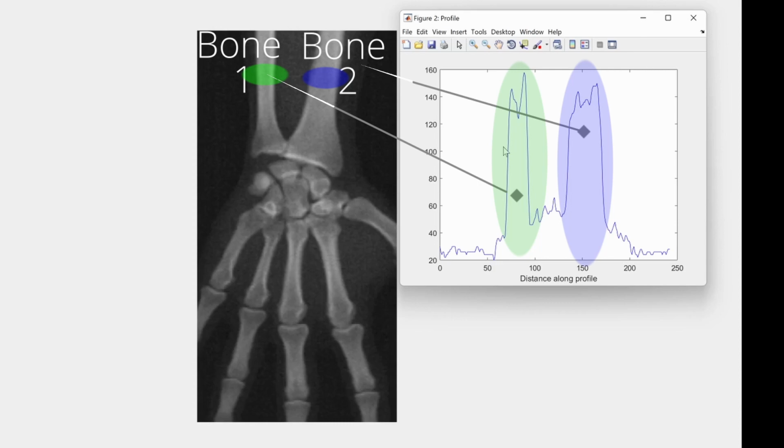They need to identify and isolate just the bone, okay? So you can use a technique called thresholding. So if we use some cutoff value, somewhere around here, maybe about 60 or 70 or so, a cutoff value right here.